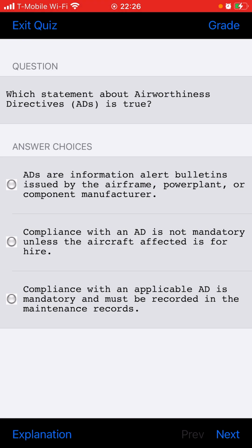What components are in a vapor cycle cooling system? A receiver dryer, evaporator, compressor, condenser, expansion valve. Why is oil added to the vapor cycle freon system? To seal and lubricate the compressor.